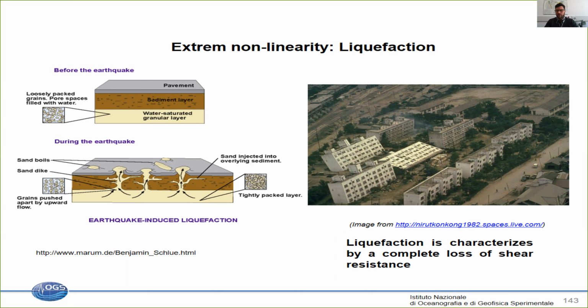So why do we have liquefaction? You can see the effect here. Generally, we have buildings with foundations. And what is happening is that the soil on which the building was founded is really liquefying. It's becoming like quicksand, so the building is not able to stand anymore. And you see here, maybe not even really damage by the shaking, I would say, but completely gone, because the liquefaction made the building tilt and collapse.